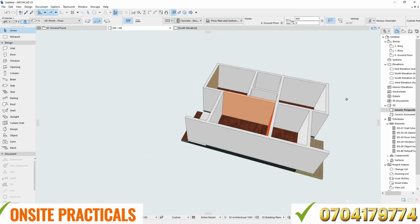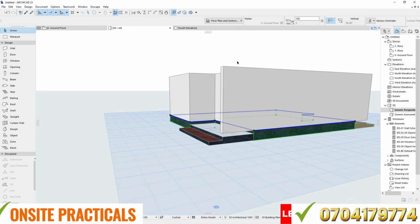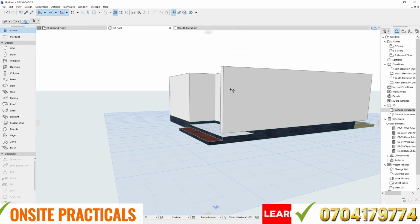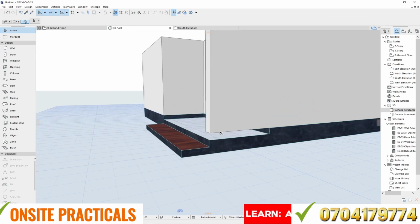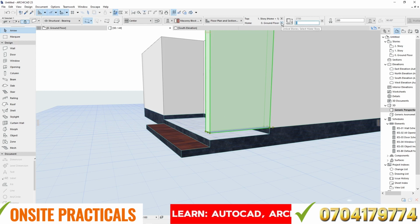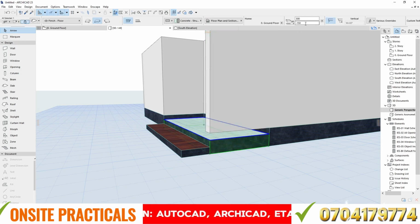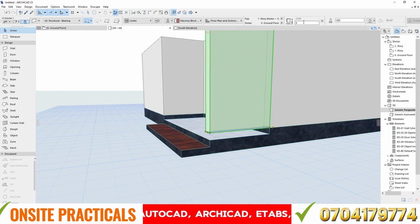your floors and everything. But then guys, the last and most important is I told you about the height of walls. You see guys, here we have this wall is actually kind of hanging. So what are you supposed to do? You're supposed to come here and you see bottom offset to the home story. Now here guys, I'm going to put the value of what exactly we have here for this. You see this floor has a negative 150. That's what exactly I'm going to come here and have negative 150.